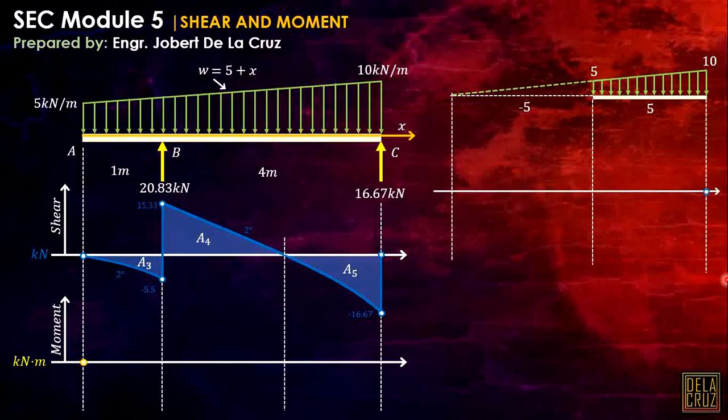Okay? So, considering na buo yung triangle natin dyan. Okay? Got this one. So, the moment here, because of that whole triangle, the moment diagram, that will be the area of this load. So, 1/2 of 10 times 10. Ano yung value na yan? That will be 50. Okay, disregard muna natin yung mga sign dito.